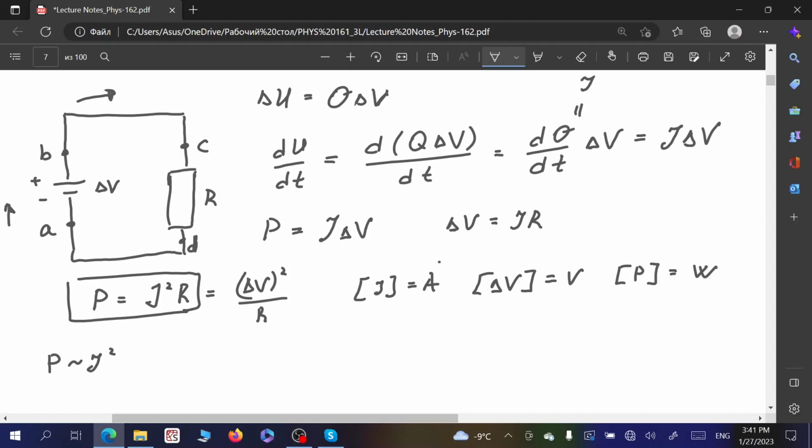So it includes the time of flight, the effective mass of charge carriers, which is defined by the real mass of the charge carrier in vacuum and the interaction between this charge carrier and the crystal lattice, and also obviously the concentration of charge carriers, which is also a parameter of the conductor material.